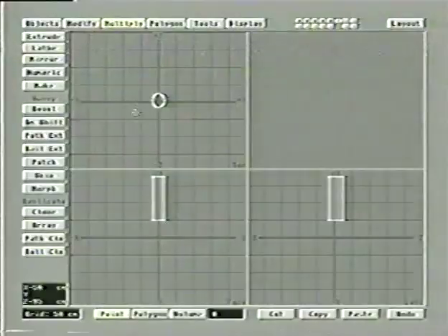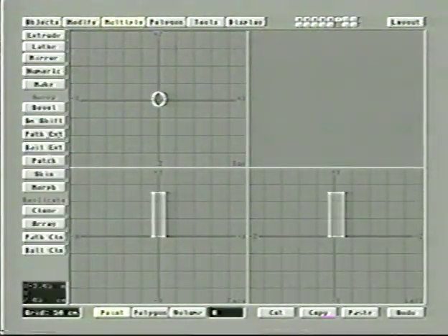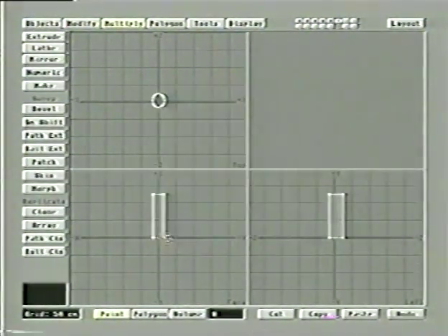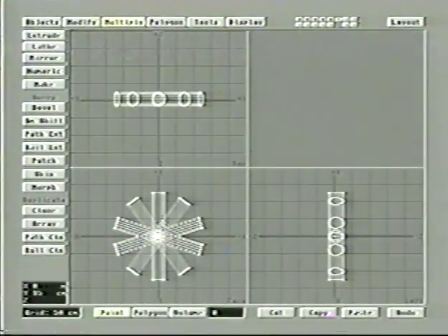Also, if we had the object in too close, let me undo what we just did and move it down a little bit here. We're going to do a very similar thing. We'll do a clone. But you notice because the object was set right here, since there was no offset whatsoever, it didn't move it that far. So sometimes you'll need to undo your clone, move the object up, then redo it for that to work.